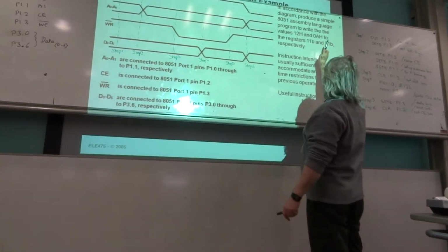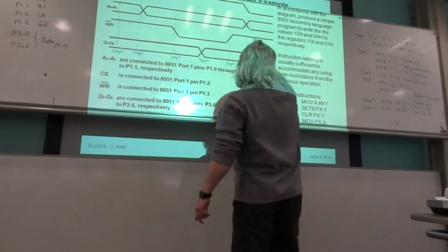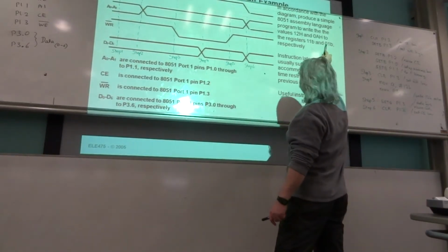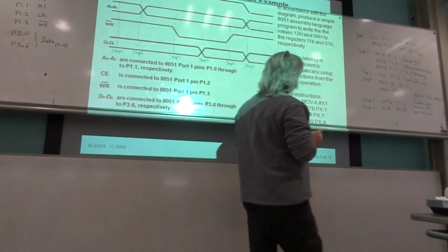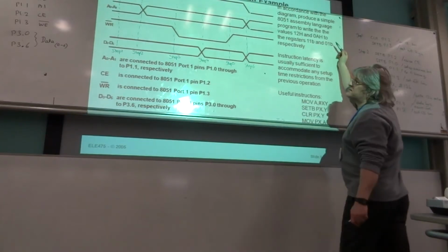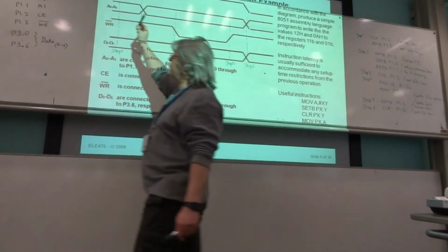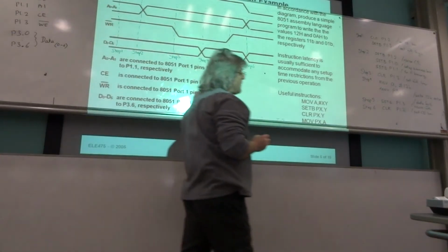And then we could write on the address bus. Now this time we're going to write the value, I think it's 0, 1 binary. We'll assume the 1 is the least significant bit and the 0 is the next one. So the least significant bit of the address bus is going to be high. So that actually already is high, but we could write it anyway. Or you could just leave it as it is.